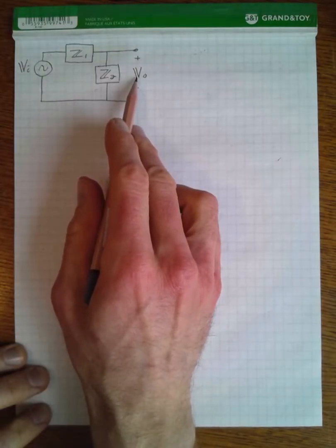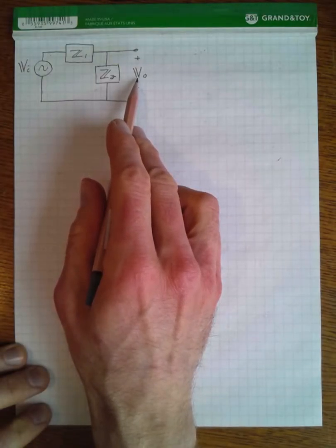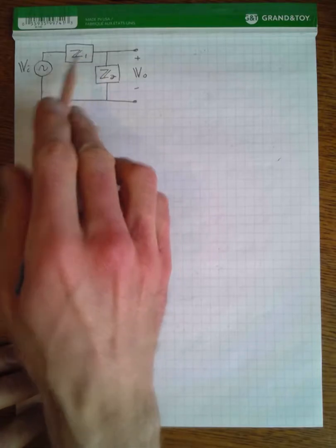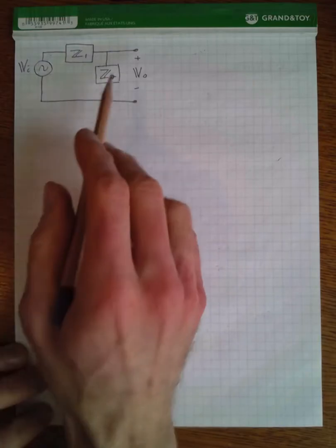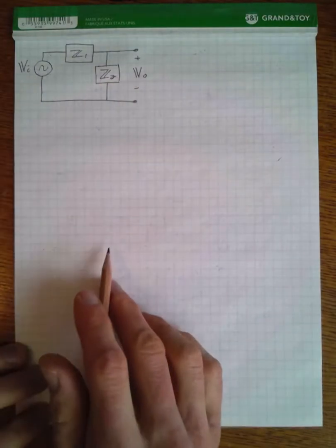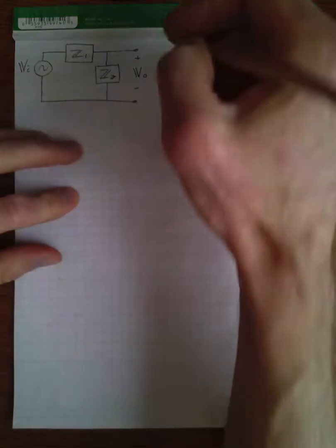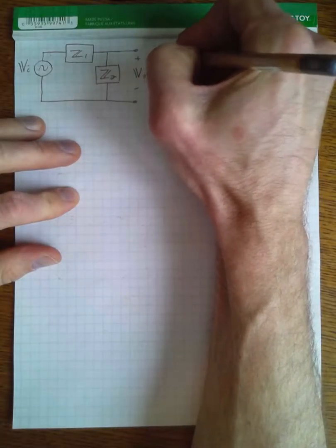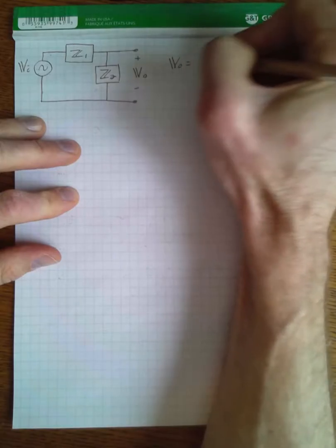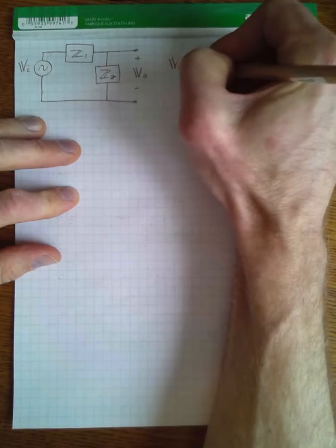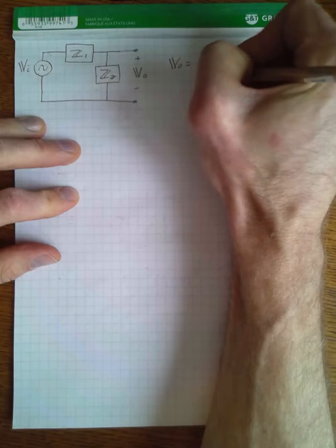And if we want to determine the output voltage, we can just treat these two impedances again just as we would resistor values. And so we can determine V out just using the voltage divider equation. So V out is just equal to the impedance Z2 divided by the summation of Z1 plus Z2